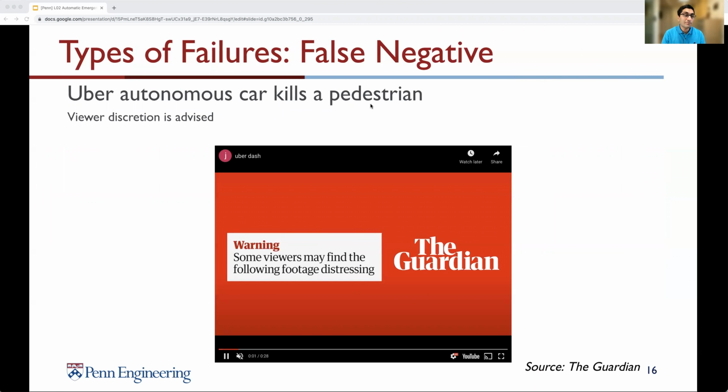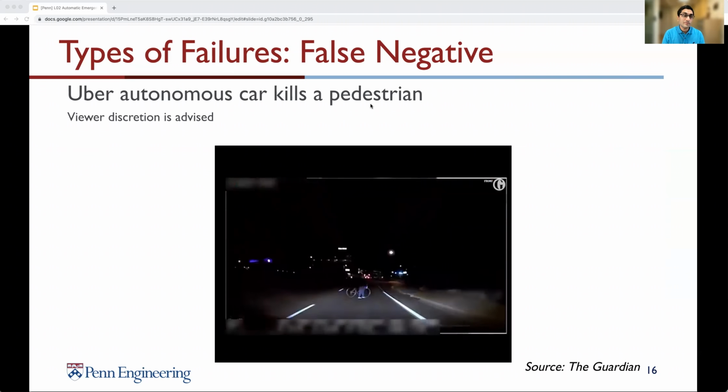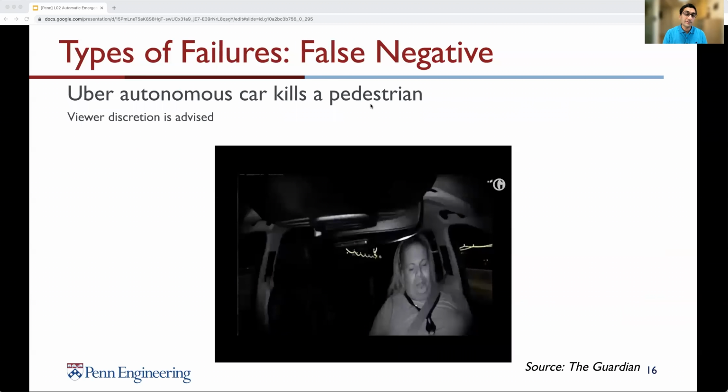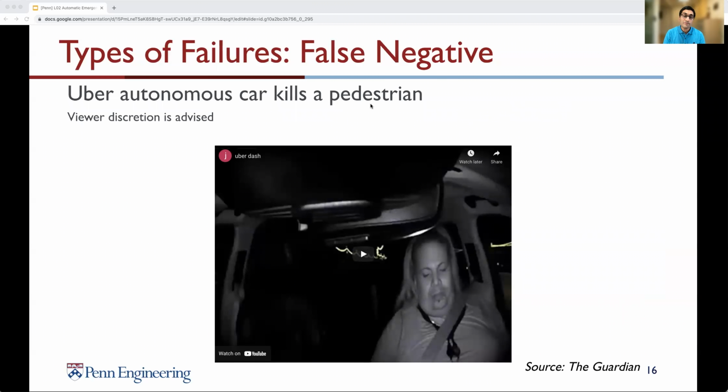In fact, let's look at an example now involving an Uber driver in Arizona, where the car hits a pedestrian. Essentially, the AEB was assumed to be active by the safety driver, and the LiDAR first detected the pedestrian about 6 seconds away. That's about 378 feet or 115 meters before impact. During the next 4.7 seconds, the self-driving system did not infer that emergency braking was needed. Emergency braking only kicked in at 1.3 seconds before the crash, but it was too late.